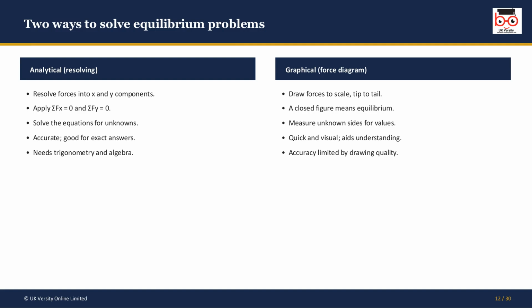If the figure closes up, the system's in equilibrium, and you can measure the unknowns straight off the page. It's quick and very visual, though only as accurate as your drawing.